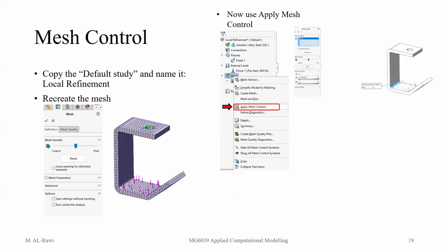And then from there, you will do the following. You select the fillet, the face you want to apply refinement to, that internal fillet. You can see the value in the chart, but you change the 1.4 to 1.2. Now that stays the same as default. You change the 1.4 to 1.2. Okay. Now, when you're happy with that, technically you just change the ratio from 1.4 to 1.2.